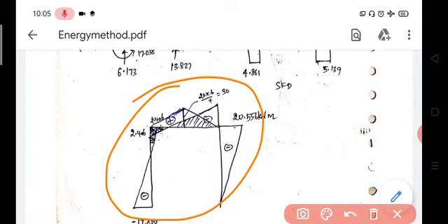So at joint A for the hogging moment you may draw a line in this direction. Then at joint B, for the sagging moment, it is drawn in the downward direction. Then connect these two lines, which represents the fixed end moment of the AB portion.